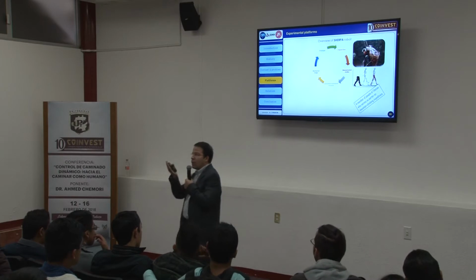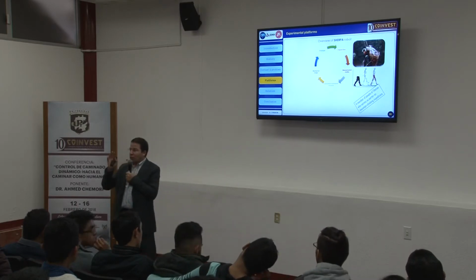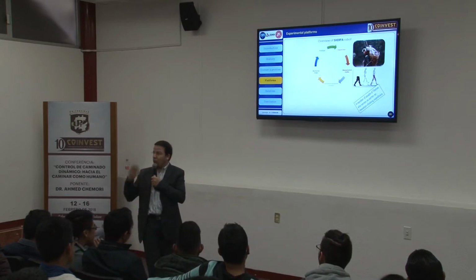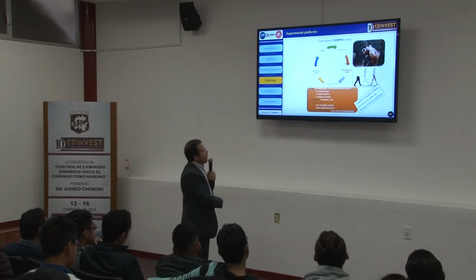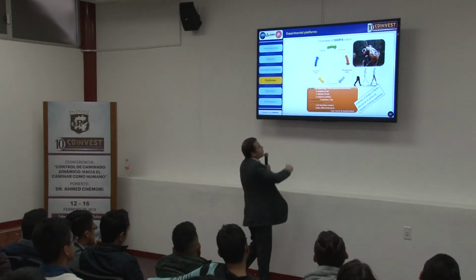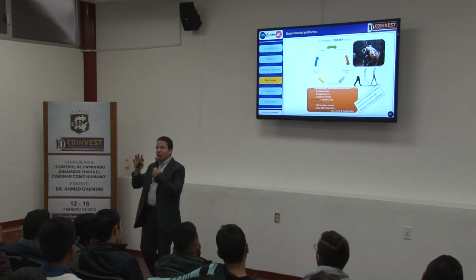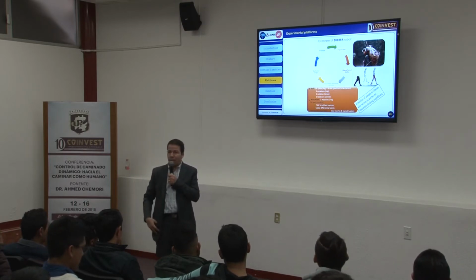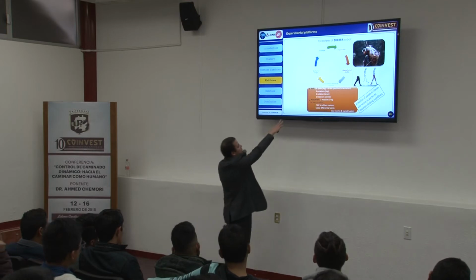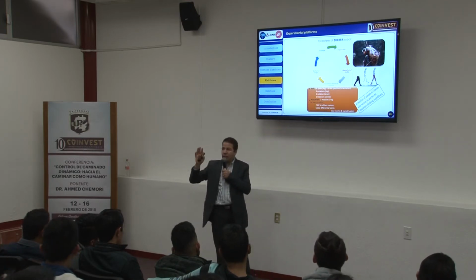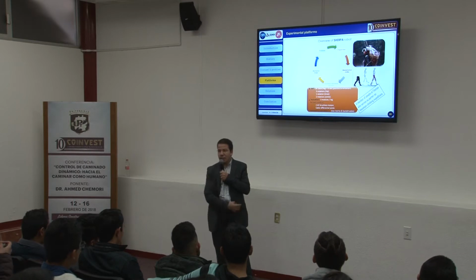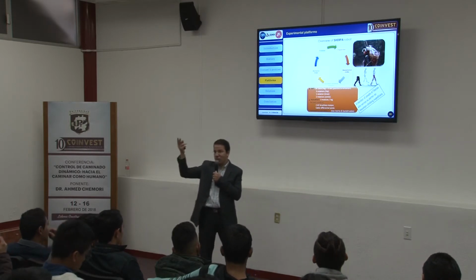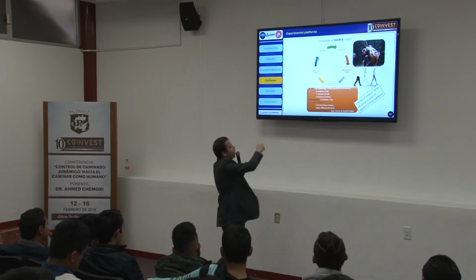So we asked them a very easy question: what would be the minimum number of joints per leg to be able to reproduce a human walking? So they made the study, and this was the result. They told us that you can reproduce the human walking through 6 degrees of freedom per leg. So we have 6 and 6, and the position and orientation of the robot in space also has 6, so 6 and 6 and 6, so we have 18 degrees of freedom.